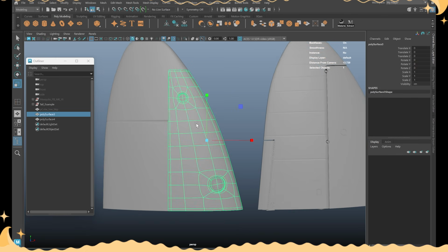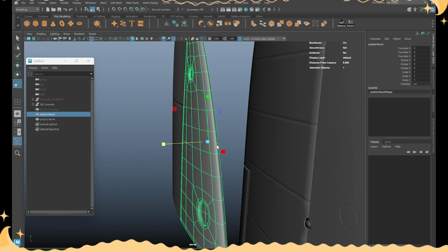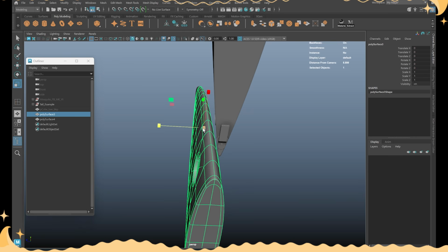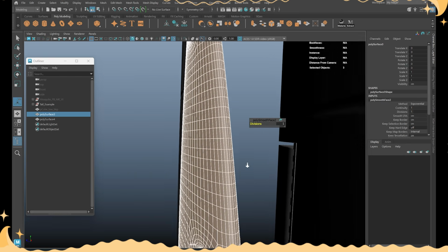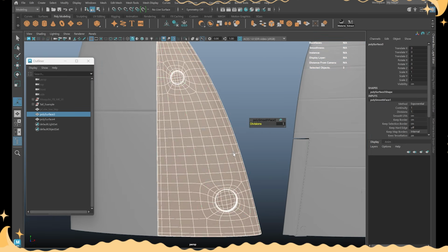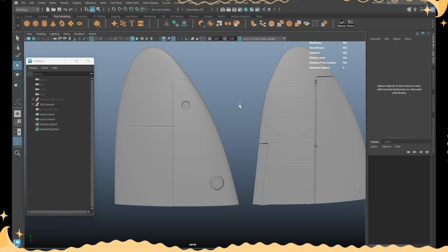And the thing I want to emphasize, as I said in other videos, is add more density if you need it. If you need to add a bunch of details on a very, very sharp or intense curve like this, where it bends around 180 degrees, then you might need more divisions. Maybe I'll just move this a couple more times like this, right? Just because you're going to need it. But if you don't, then keep it a bit more light. And yeah, the most important takeaway from this, if anything, is just start simple, block out, take your time, be patient, and don't be afraid.